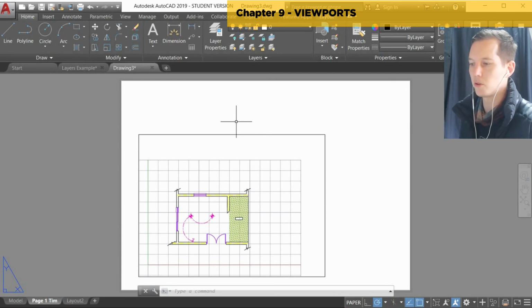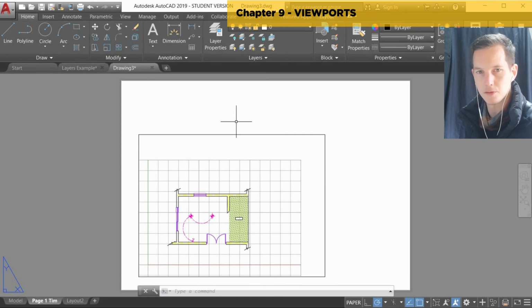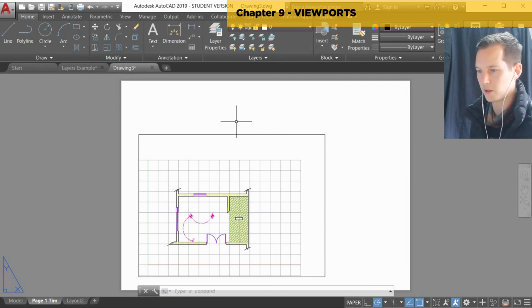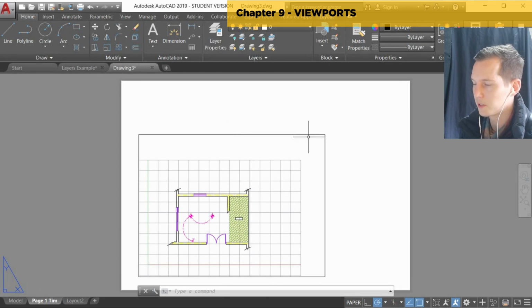And whenever you make all of these changes in AutoCAD, like page setups or setting up styles, you can save all of these drawings as template files, okay? The same way you'd save a normal drawing, a DWG file. If you change that selection to a DWT, or drawing template file, you can save it as a template. It basically functions like a drawing, but when you open it up, you can use that as the basis for all your new drawings, instead of having to reconfigure page settings and all of that every time you do a new AutoCAD drawing. So yeah, that's just a tip.